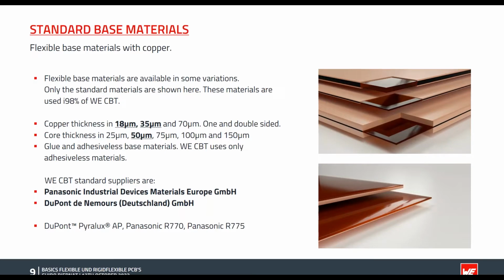Glue and adhesive base materials are also possible. Würth Elektronik uses only adhesiveless materials. Our standard suppliers are Panasonic and also DuPont. The material called Pyralux AP from DuPont, or from Panasonic R770 or R775. This base material is one polyimide core in the middle and double-sided copper.